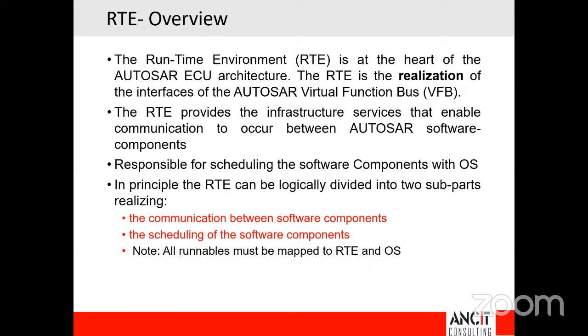Second, RTE is also responsible for scheduling of the software components. Instead of calling it scheduling, all runnables will be triggered. In C we know that all statements are executed in a sequential fashion, line by line, which will not be good for an automotive standard. That's why we have a runtime environment and an operating system. So the entire scheduling of all the runnables in the software components will be done by the runtime environment. That's the whole idea.